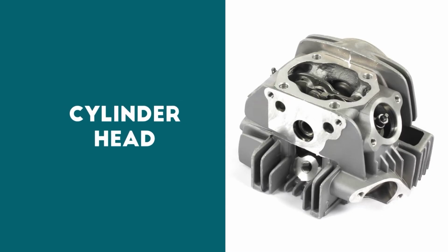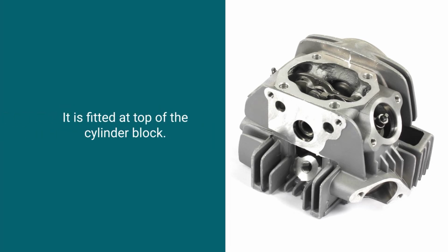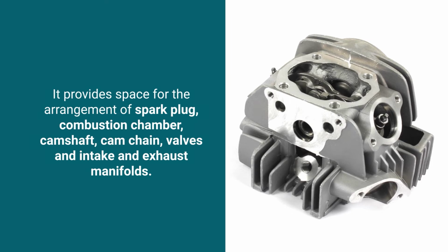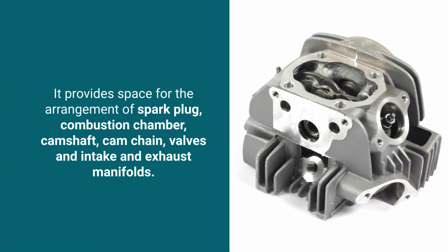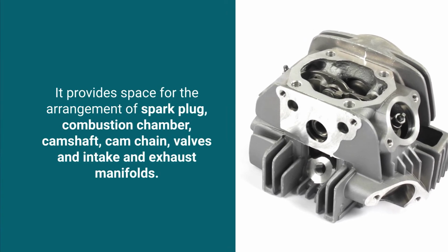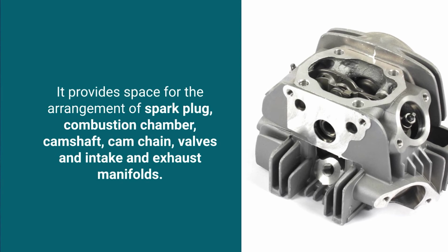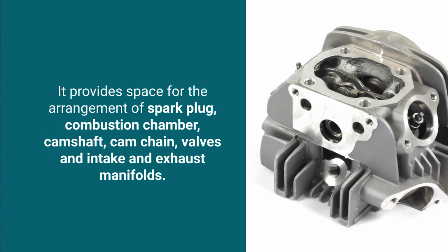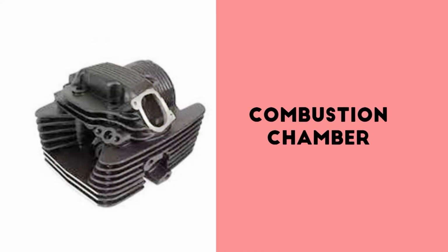This is one of the important parts. This is the cylinder head. It is fitted at the top of the cylinder block, and it provides the space for the arrangement of your spark plug. Combustion chamber, camshaft, cam chain, valves, intake and exhaust manifold, all these are provided or fitted in the cylinder head.